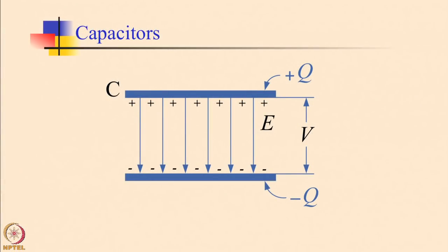Now there are three types of dielectric material which are in use. One of them is polystyrene, the other is polycarbonate, which has a dielectric constant of something like 3, and polypropylene is very useful, it has really turned out to be a very superior quality dielectric. It has a dielectric constant of something like 2.3. The dielectric loss is very low in both polycarbonate and polypropylene type capacitors.